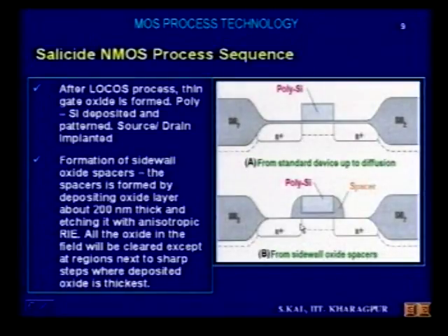In earlier cases you have seen, we again open a window, oxide is deposited here, and open a window on gate, and there you deposit metal. So there you are wasting some of the gate area. So in self-aligned process or high density MOS process, that area has to be saved, so that you can increase the density of the components by reducing the size of the MOS transistor.